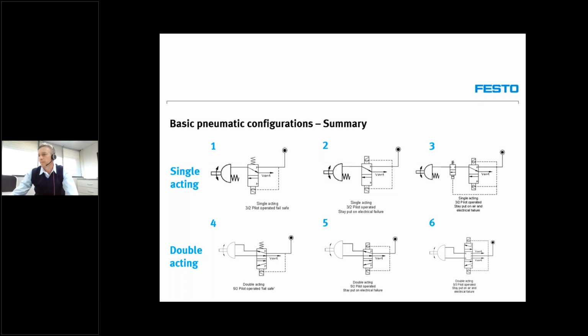Yeah, I think it's a very big topic, and we can discuss a lot on this, and that's actually where the value of your course comes into play. If you consider the spring pack inside the actuator that I spoke about to make it fail open or fail close, behind that, you can also use an air receiver to create the same functionality. In many plants these days, the end user does not want a mechanical spring pack to cause the device to fail open or fail close, because it has inherent risks.